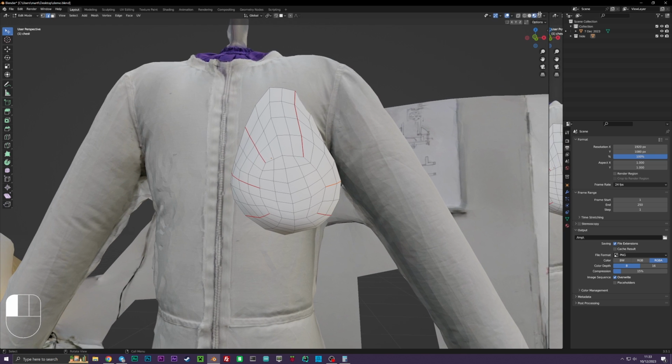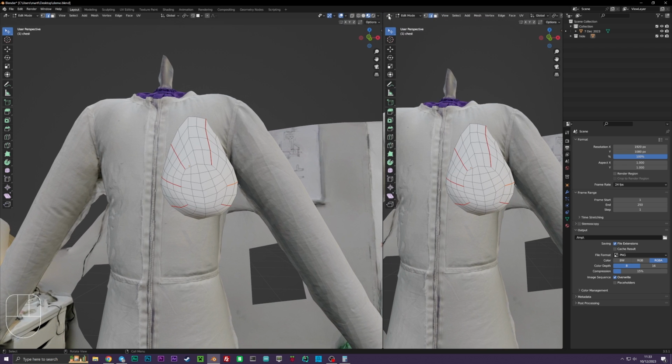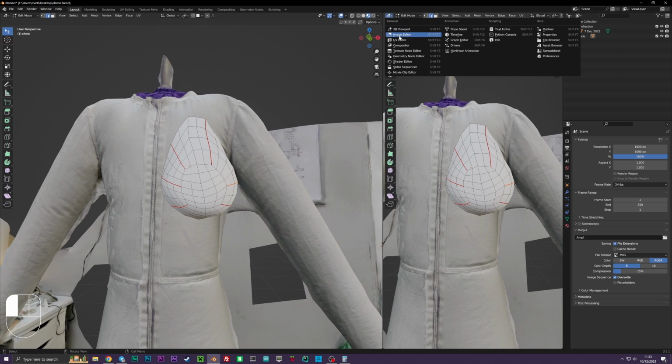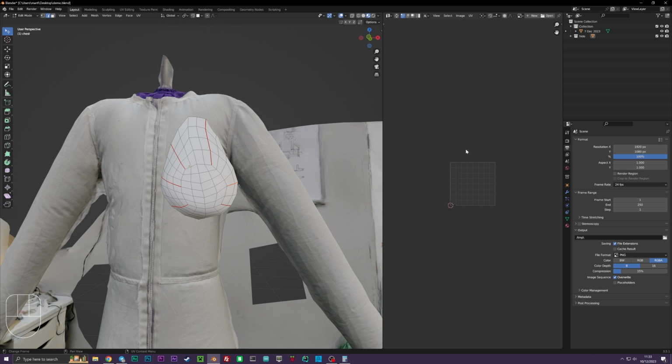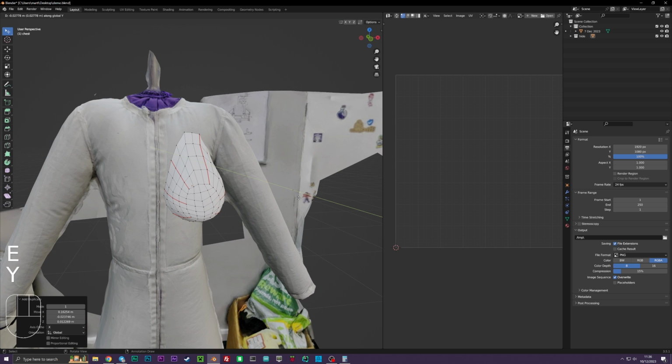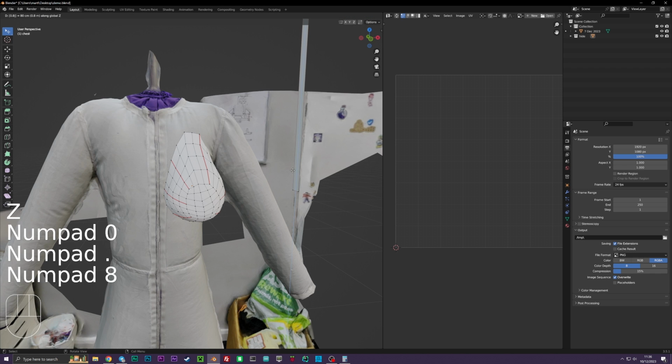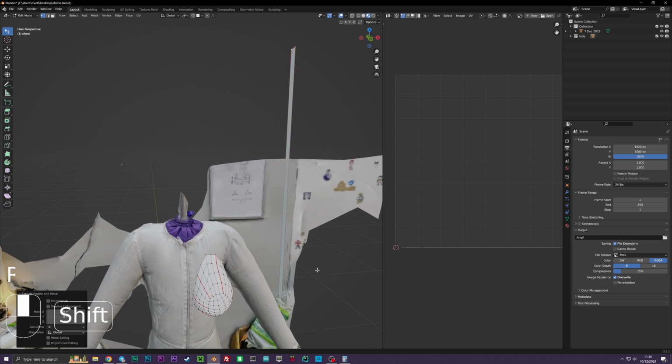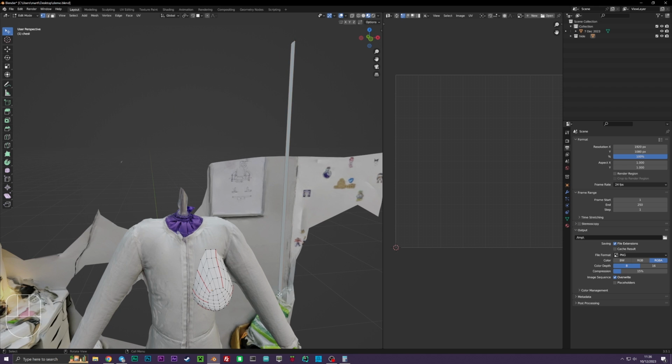Once you're done, drag out a second window using this impossibly tiny triangle and use the drop-down to select UV Editor. This is where we can see and edit our pattern. First, we need to make some secret meshes that'll help us later. Duplicate a vertex and use it to make two rectangles. It doesn't matter how wide they are, but make the first one 800mm tall and the second 200mm tall.